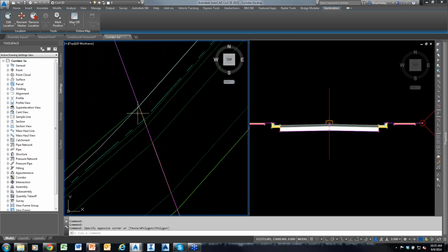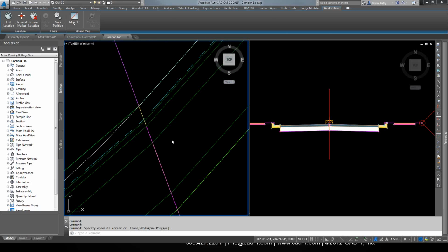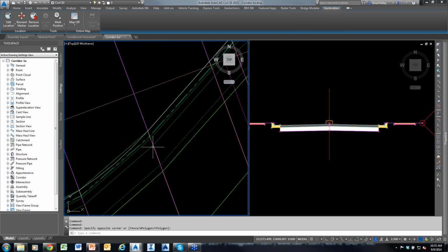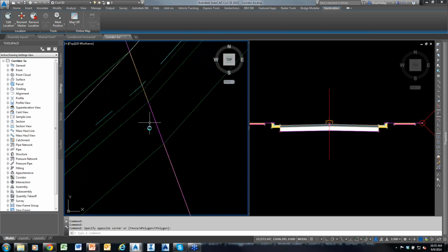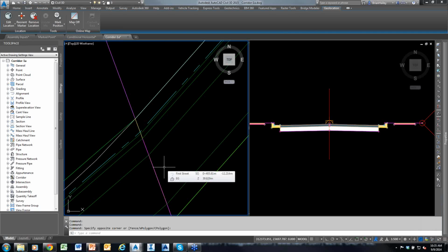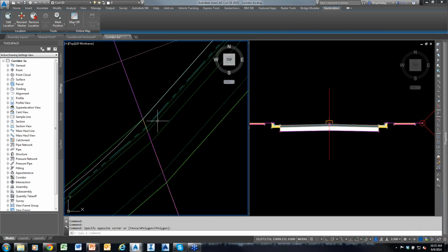All right? It goes from here to there, 1.5 feet, 2 inches, 4 inches. I don't want it to be relative to my center line alignment. What I want it to do is go from here and angle so it's perpendicular to that target, 1.5 feet, 2 inches, 4 inches. So using an assembly offset, you can do that.